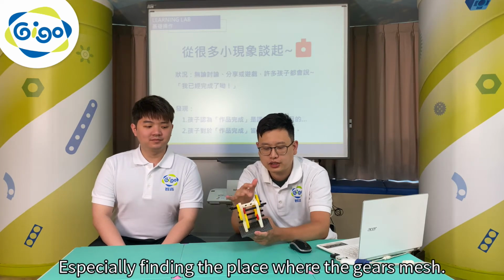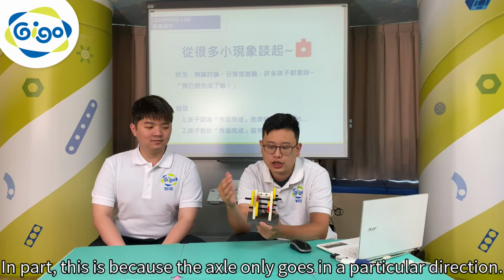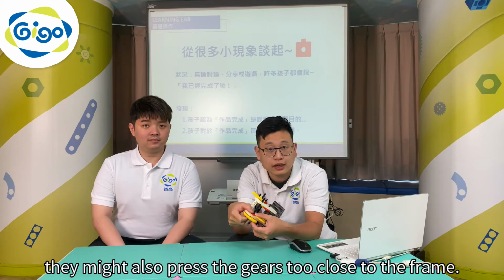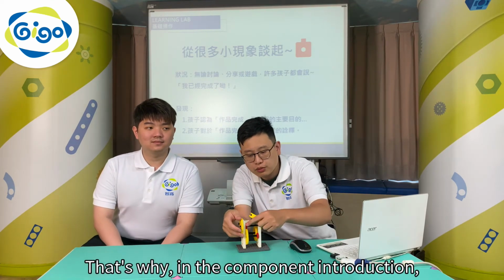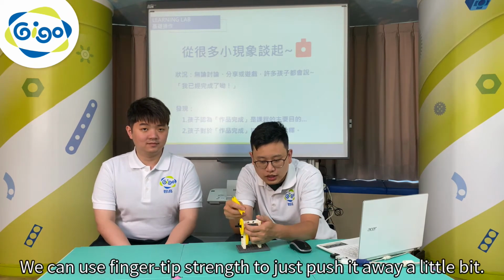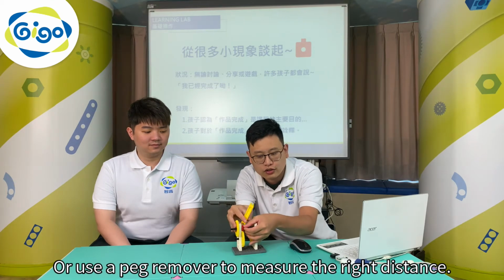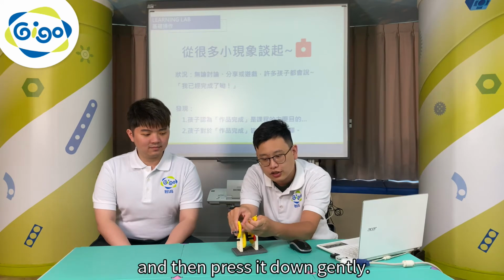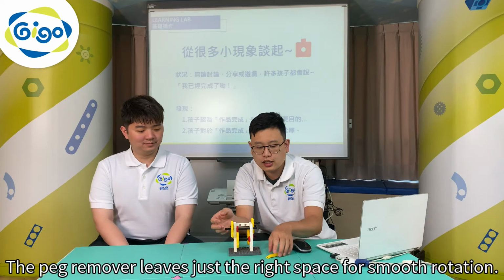especially finding a place for the gear mesh. In part, this is because the axle only goes in a particular direction. When children are building, they might also press the gears too close to the frame. That's why, in the component introduction, we provide a solution for this. We can use a fingertip to just push it away a little bit. Or use a peg remover to measure the right distance. Insert the peg remover here and then press it down gently. The peg remover leaves just the right space for smooth rotation.